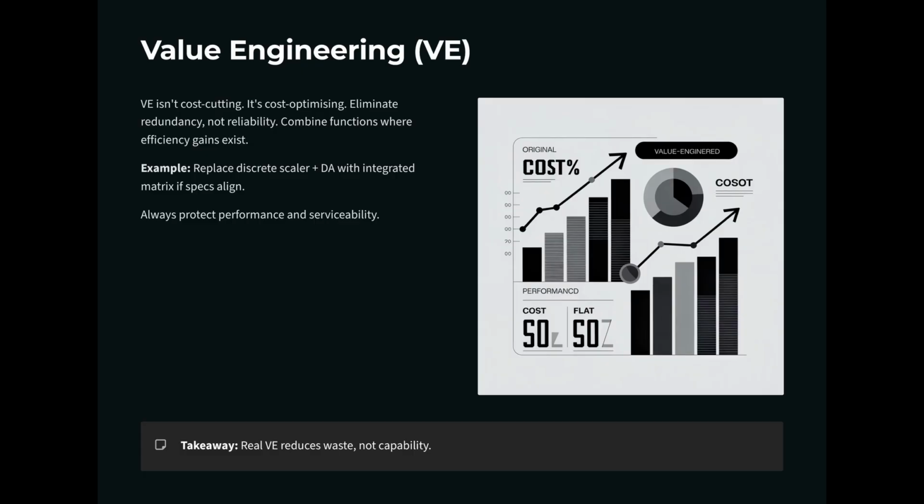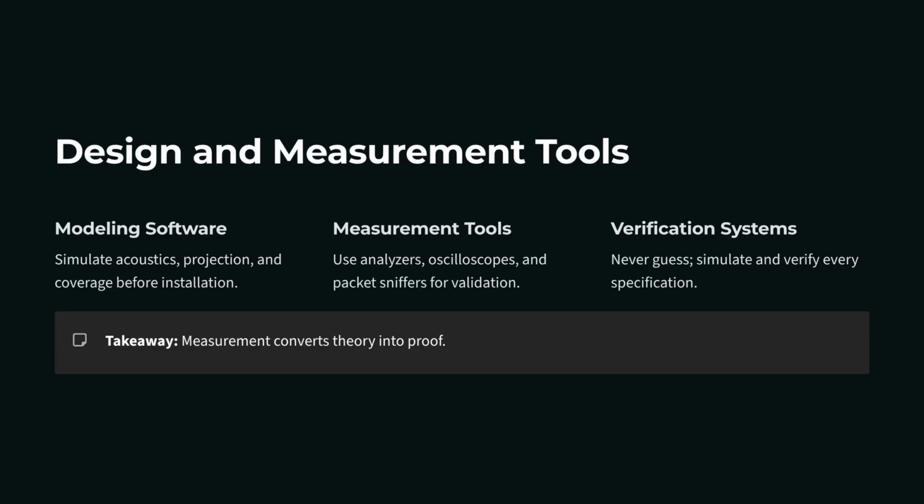And always remember that design accuracy depends on measurement discipline. Use modeling software for acoustics, projection, and coverage. Use spectrum analyzers, oscilloscopes, and packet sniffers for validation. Never guess. Simulate and verify. Because in the end, those measurements convert theory into proof.